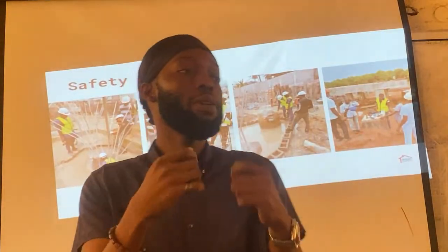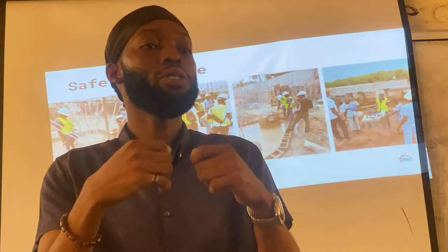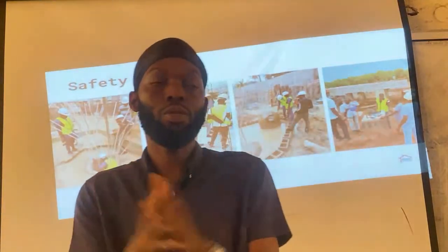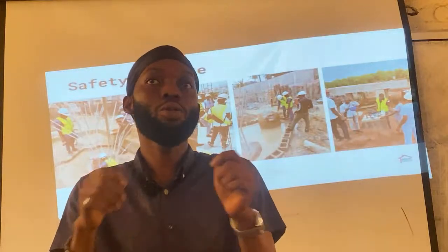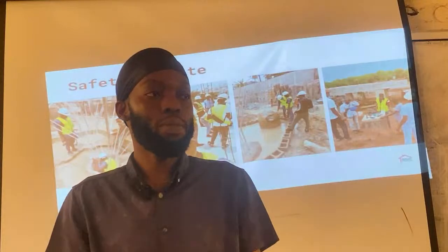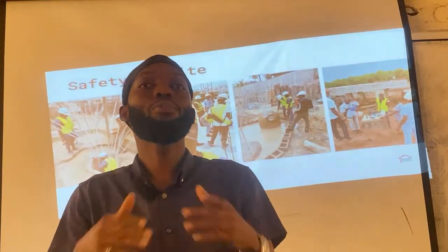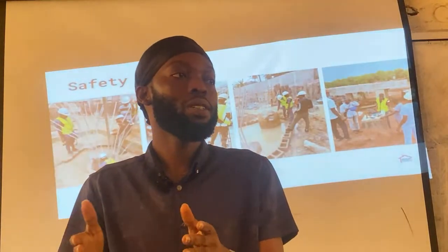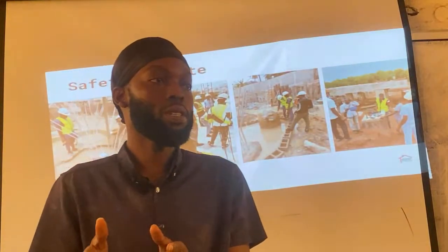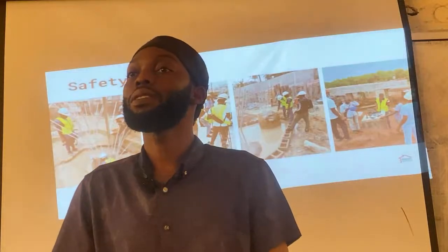That's just like a permeable membrane that will rub on the transducer. Couplant, we will explain all those later. That's the only thing that can stain the wall, but it can be cleaned because it is water based. But if it is something that is vibrating the building, it's definitely not non-destructive testing. You understand?